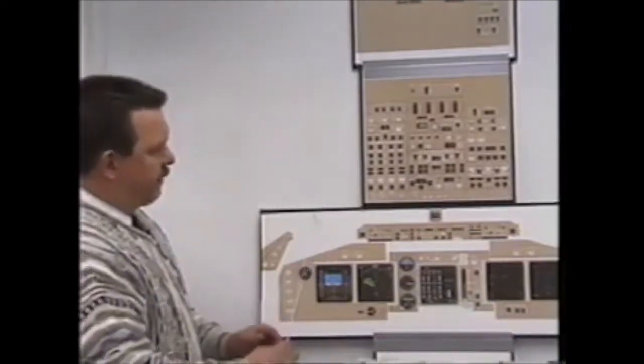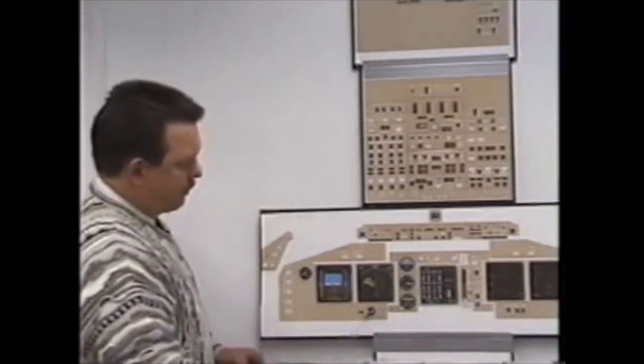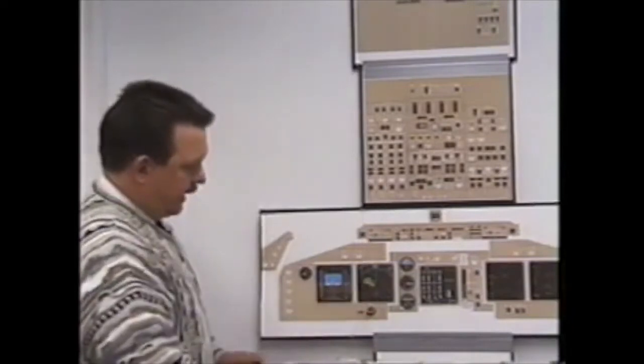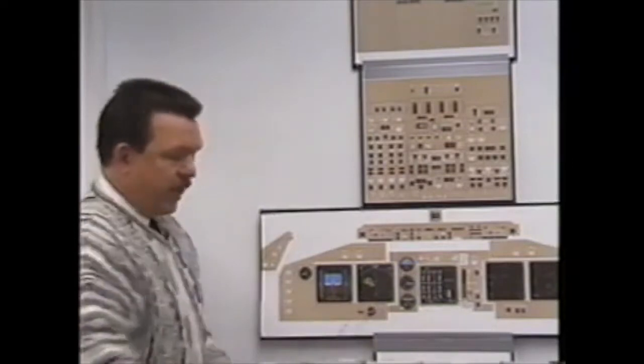So what we've done here is I've gone in reverse order of priority. System 2 started it out, could not bring up the gauge. Pressurized 1, 1 took it from 2, again cannot bring up the gauge. Pressurized 4, 4 takes it from 1 and brings the gauge up.